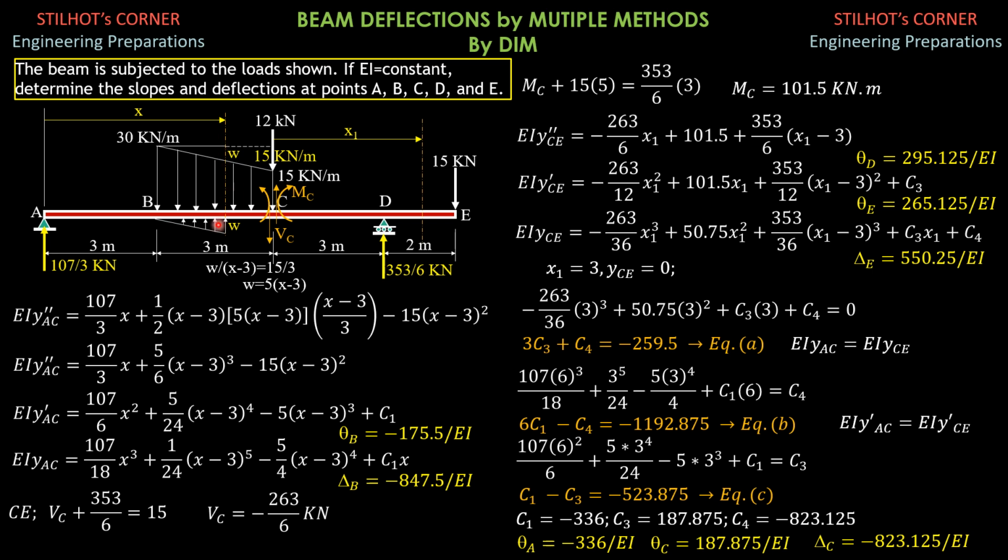The beam is subjected to the load shown. If EI is constant, determine the slopes and deflection at points A, B, C, D, and E. So by double integration method, I set up two differential equations for the elastic curve.